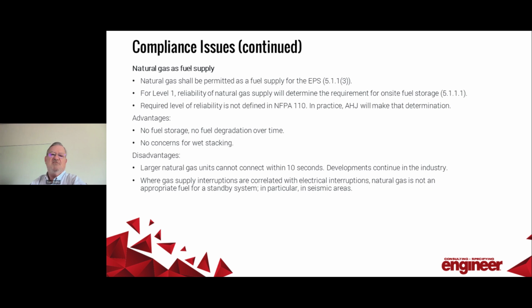Now, can natural gas be used as a fuel source? Yes, it can if the supply is reliable. There's no required level of reliability or even clear definition in NFPA 110, so normally an AHJ will make that determination. Natural gas can offer some distinct advantages. First, there's no on-site fuel storage, and that means there's no concern about maintaining fuel quality over time. And wet stacking is not a problem for natural gas generators. There are disadvantages too, like larger gas generators cannot connect within 10 seconds, making them unsuitable for emergency loads, though the industry continues to advance in that regard every year.